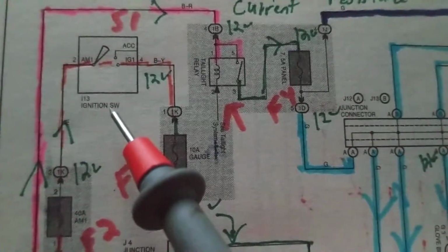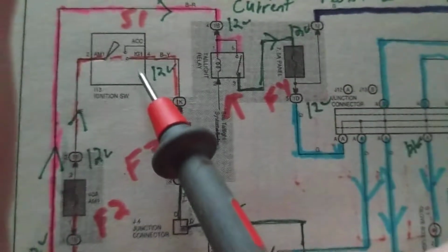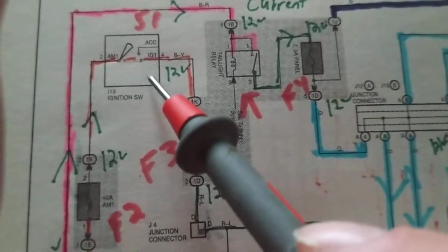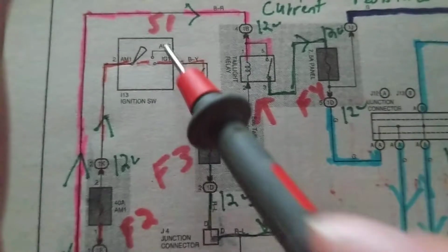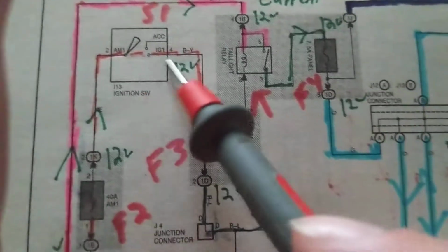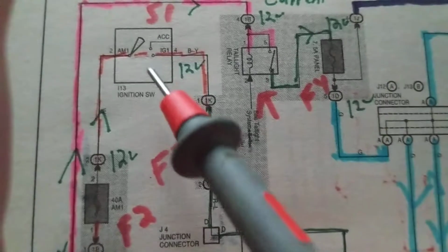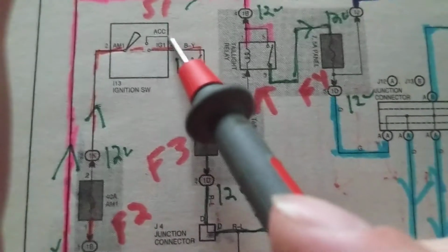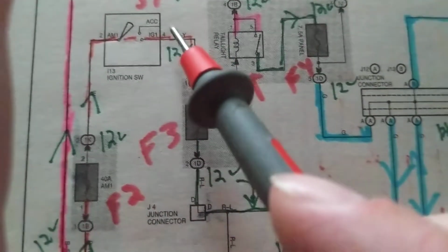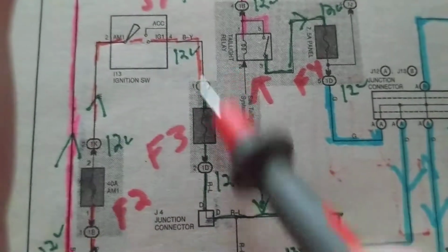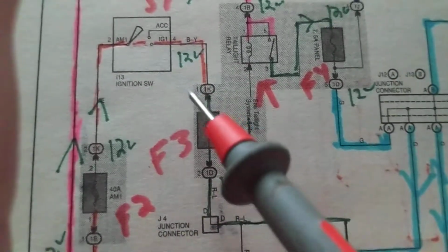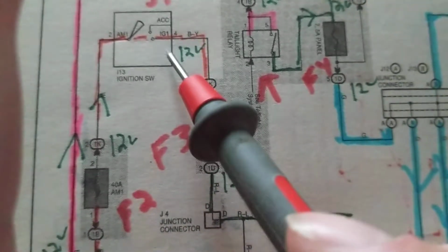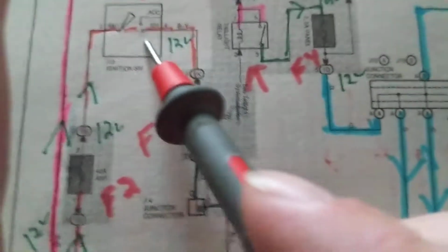Question. In what position does the switch have to be to crank the engine? Technician A says in accessories. Technician B says in ignition or start. Who's right? Technician B. Has to be in ignition. In accessories, all you have are the lights working, the fans working, and things like that. It does not crank the engine. You have to crank the starter. Sometimes instead of ignition, you'll have start, it'll say, or run or start. This has to be closed. The switch has to be closed.